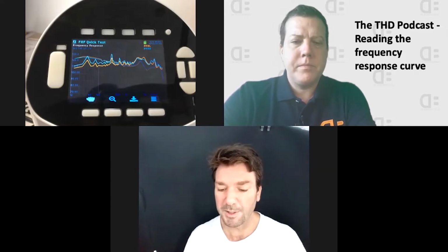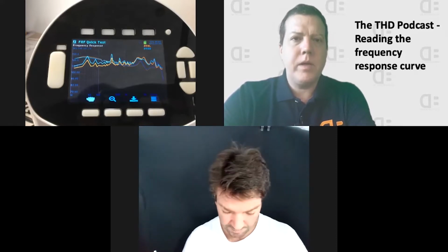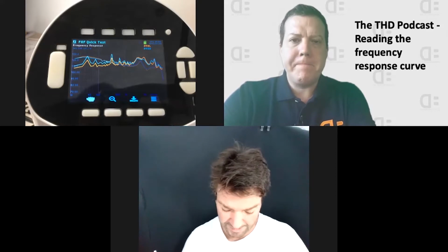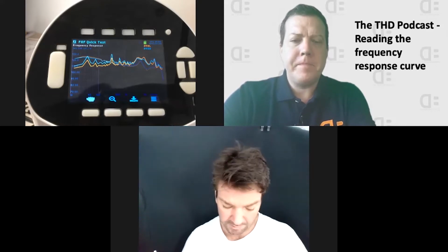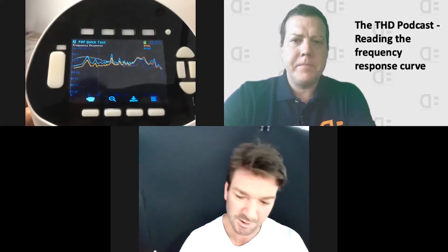You'd have very, very strong bass. Any tiny movement by that speaker diaphragm would just increase the pressure in your ear canal. You never really get that because there's always some tiny amount of leakage at some point. Even if you have a very well sealed thing, you pump some air pressure into it, it slowly dissipates over time. And I'll go back to these ones.